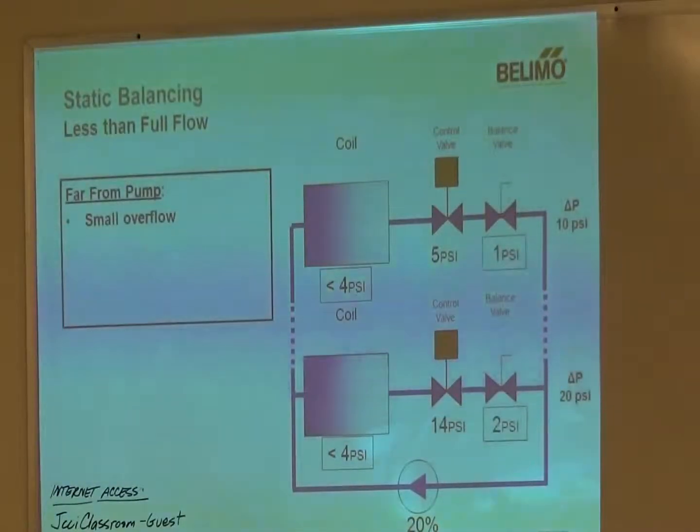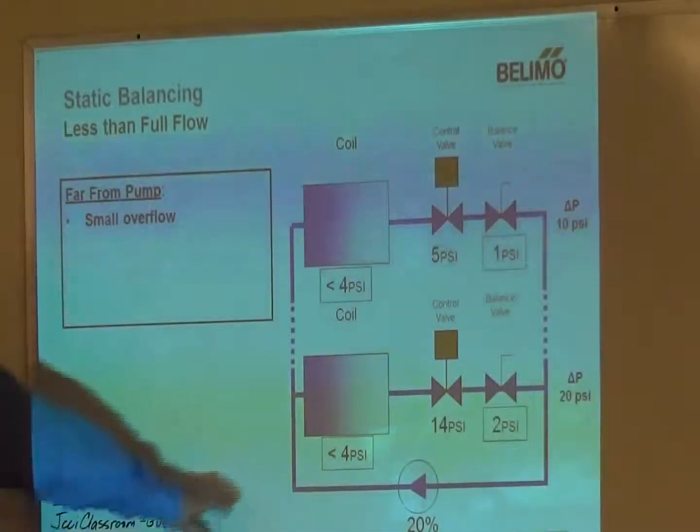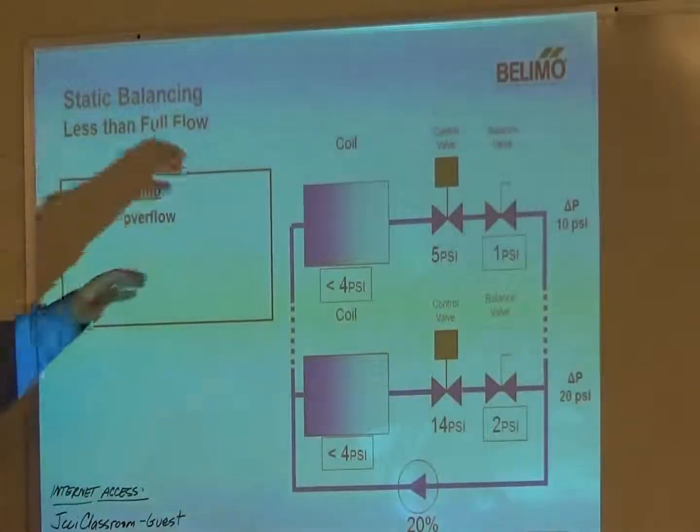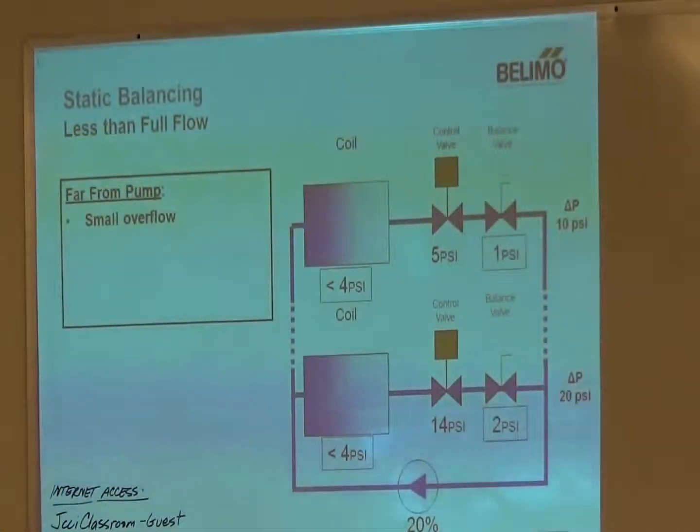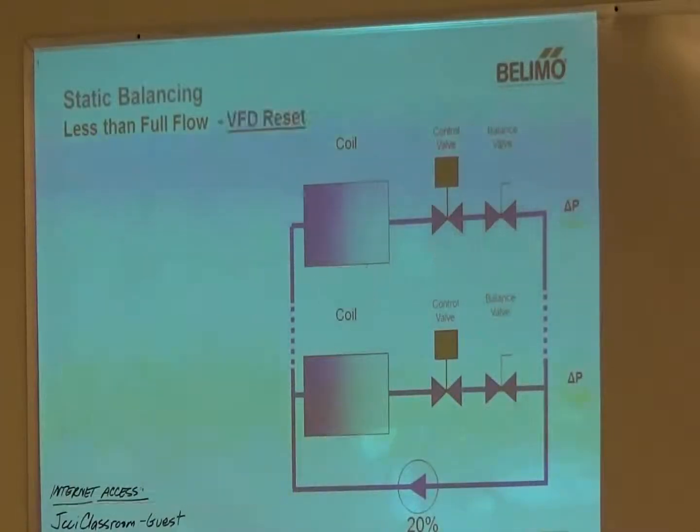You get close to a pump, close to your source, you're going to have high pressure. You get further out the system, you got low pressure. That's why we put our pressure sensors out in front of the line, so we guarantee we get our flow out there.